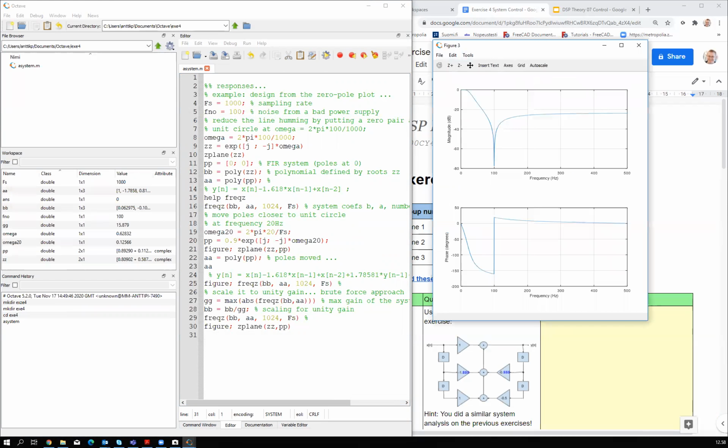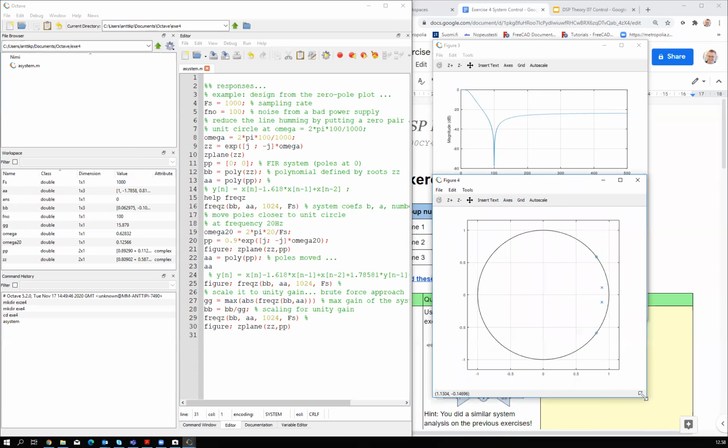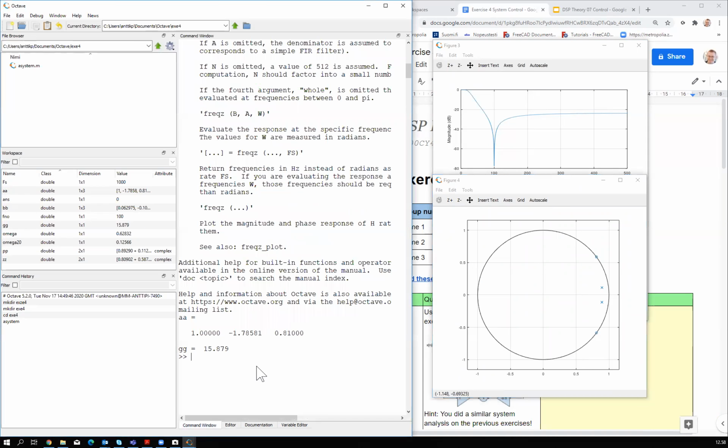So I have this kind of low pass filter as a second order system. Based on the location of these poles, I would guess that this actually has some overshoot. Let's see how much it does have. So we calculate the step response the old-fashioned way. I start from -10, go to, for example, 100. So this is our region of interest in samples.